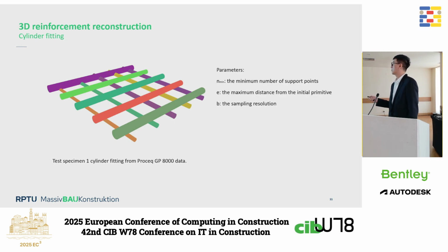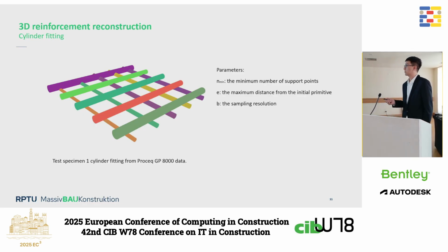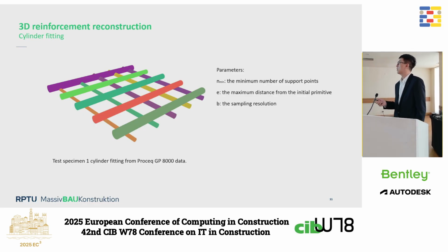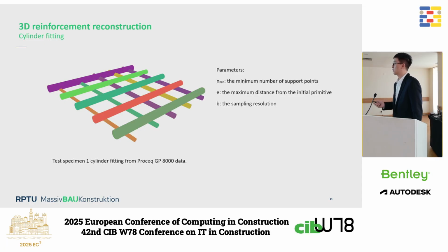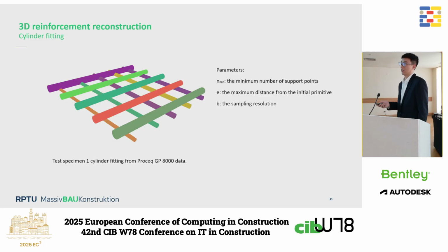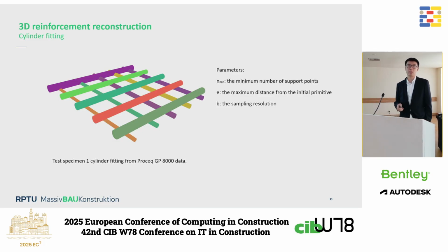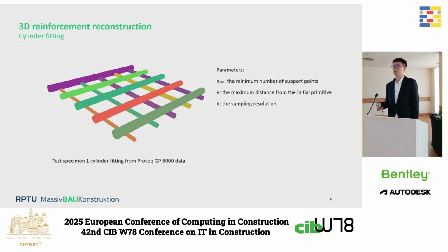For the input parameters of this RANSAC algorithm, we have determined three important parameters. One is the minimum number of support points, another is the maximum distance from the initial primitive, and then the sampling resolution. And we have successfully fitted the number of rebars, I mean the correct number of the rebars.